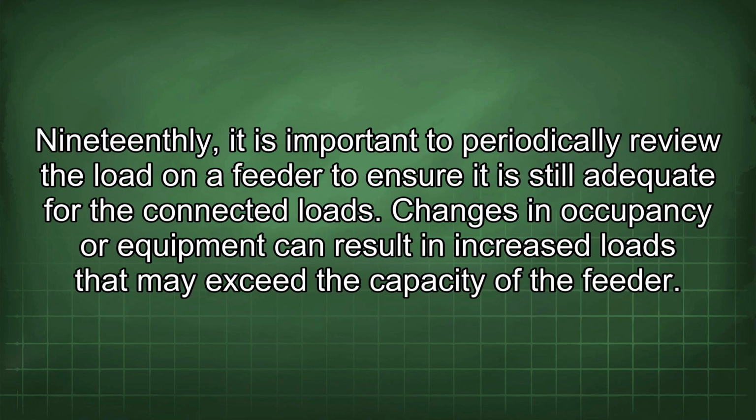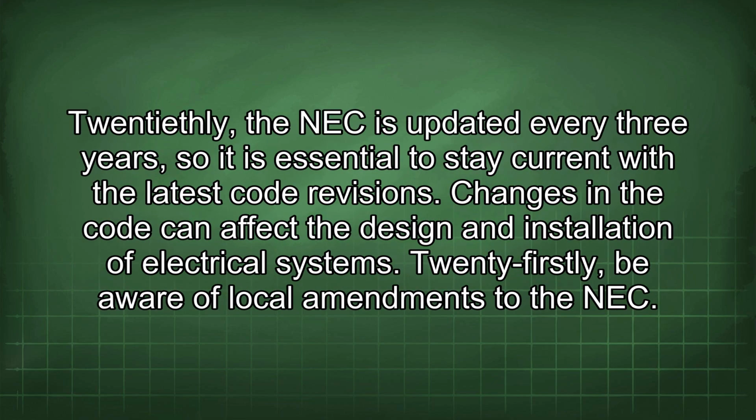19thly, it is important to periodically review the load on a feeder to ensure it is still adequate for the connected loads. Changes in occupancy or equipment can result in increased loads that may exceed the capacity of the feeder. 20thly, the NEC is updated every 3 years, so it is essential to stay current with the latest code revisions. Changes in the code can affect the design and installation of electrical systems.